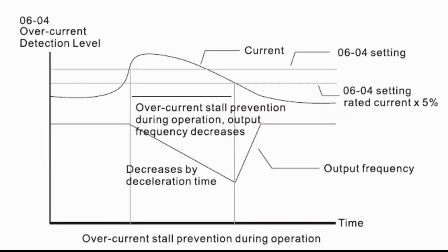These are applications in which if you increase the speed, the load also increases. Actually, it's not proportional, it's quadratic. It does not work in constant torque applications. In conveyors or other similar applications, it makes no difference if you decrease the speed, the output current will not really decrease that much. So keep in mind that this function can only be used on variable torque applications. Okay.